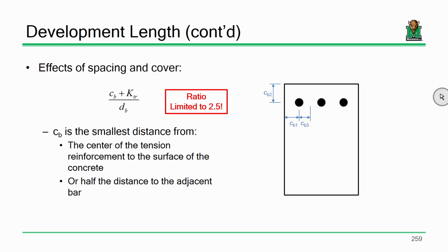It depends on the type of stirrups that you're using. It depends on the size of the bars that you're using. It also depends, keep in mind, on your environment. It's a different scenario for beams inside of a building than it is, say, piers on a bridge in Miami where you're exposed to saltwater conditions and those covers have to change quite a bit, or beams in a corrosive environment. So my answer to you is that it depends on your cover requirements and what's actually there.